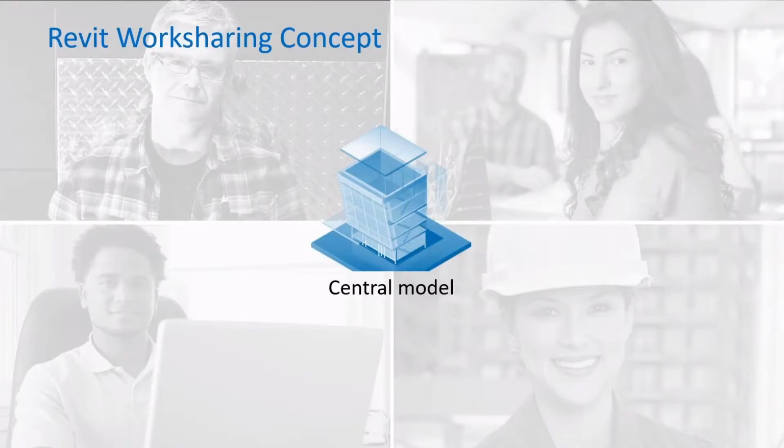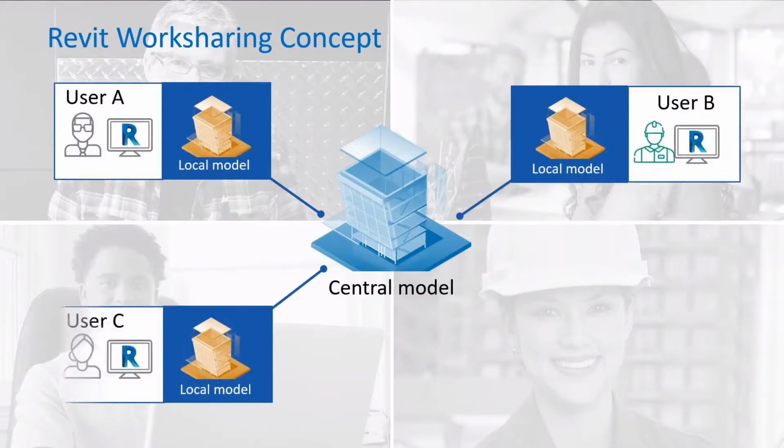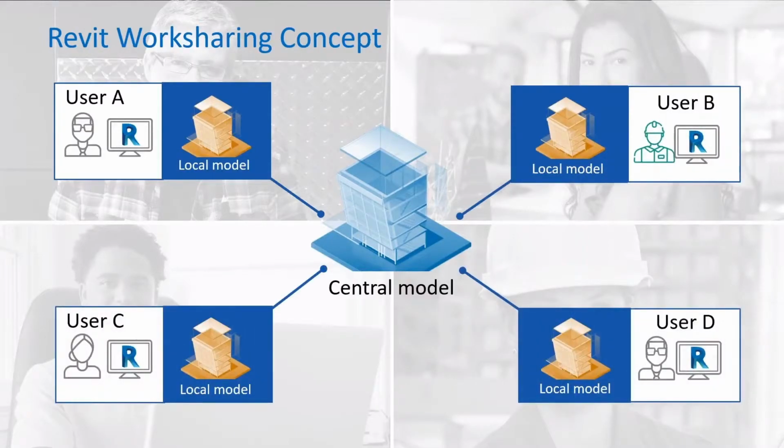So essentially the concept is work sharing, worksets, save to central, reload latest, relinquishing objects, claiming objects. Essentially you have a central model, you have different users with their local models, and they're going to communicate with this central file, if you will.